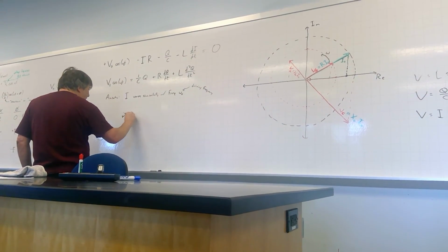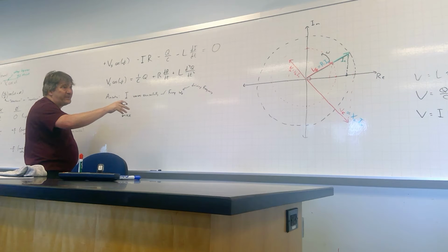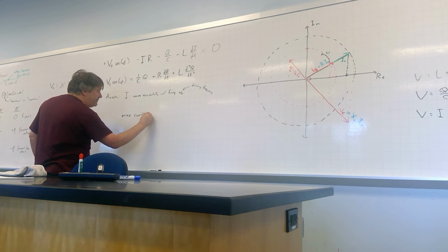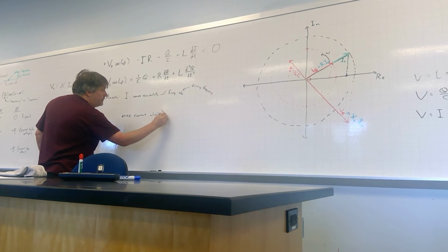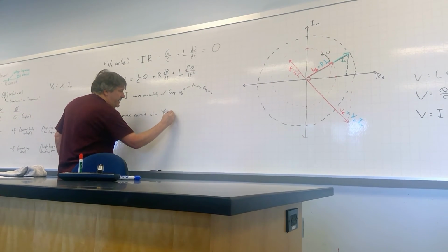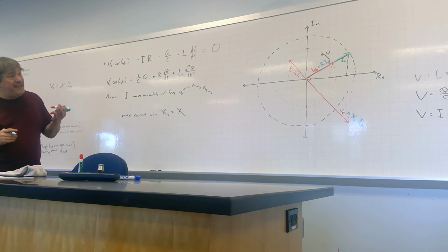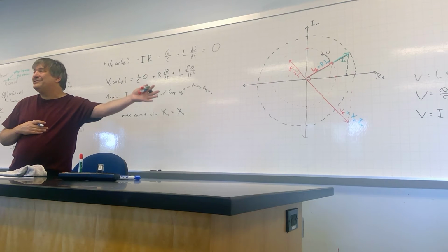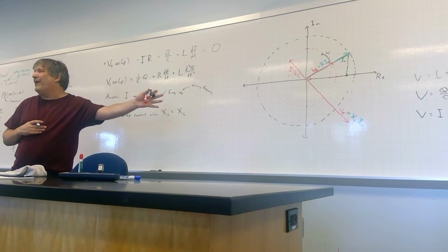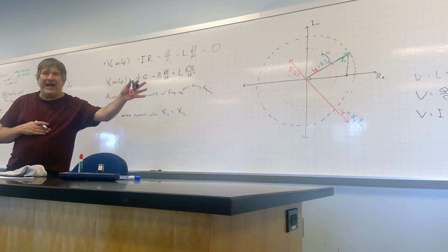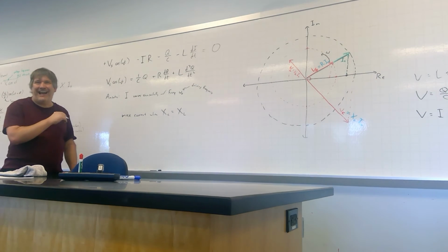It turns out, if we've done everything correctly in our little geometric walkthrough of the solution, I will get the maximum current when the impedance of the capacitor is equal to the impedance of the inductor. Then the impedance of the whole circuit will just be R. The resistor will be the only thing left contributing impedance. The capacitor and the inductor will have canceled each other out.